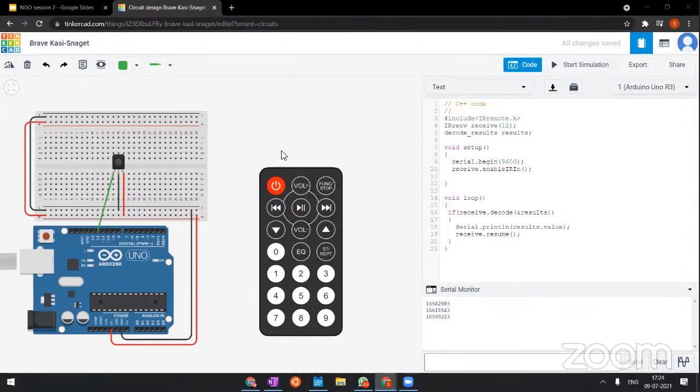Okay, so I'll just explain what we're planning to do with this. Now we have the remote, and we can receive a signal from the remote, and we know how to decode the signal for each button. So now we can repurpose each button such that if it is pressed, I want to do something. Usually these decodings are printed as something called the hex value. The hex value of each remote would be different, but not all remotes will have unique sensors. For example, there'll be a range of values for a manufacturer. If you take Sony, almost all Sony products will come into that range. You take Sanyo or Panasonic. I think there's also a library in which you can cross check what type of remote yours is.